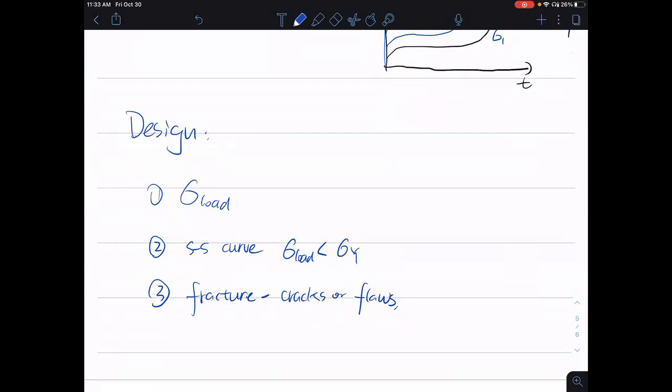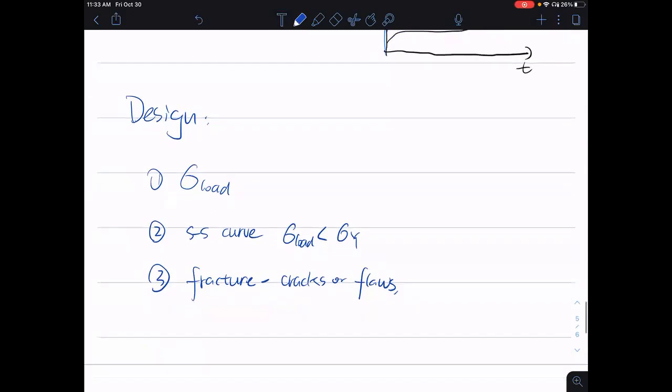You end up with a much larger stress along the cracks that could cause crack propagation and lead to fracture, even if the load you apply to the whole material is less than yielding stress. So that's the first thing you need to check: did I consider flaws in the material?